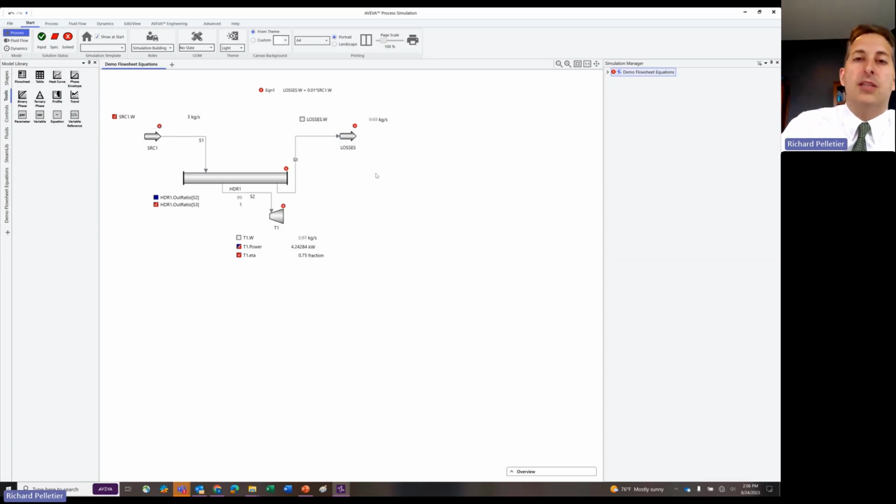And then if you take this out through all the different relationships, the program's able to know that I've added an additional constraint to my simulation. I have one too many things specified here now that I'm imposing this additional constraint through this equation, right? And so the program tells you, just as it does any other model and variable within the software, that you're overspecified and you have to remove a spec.